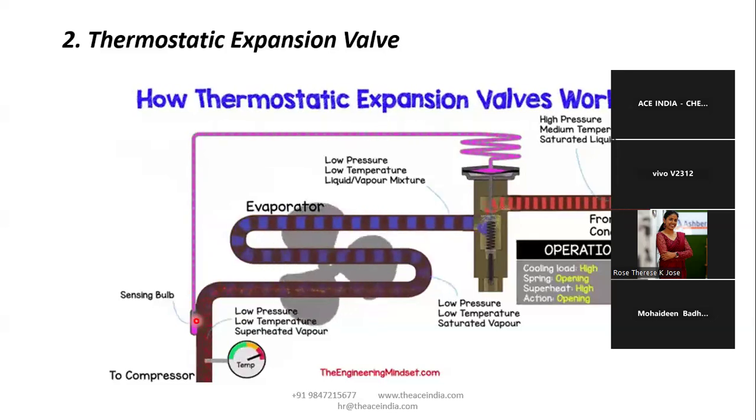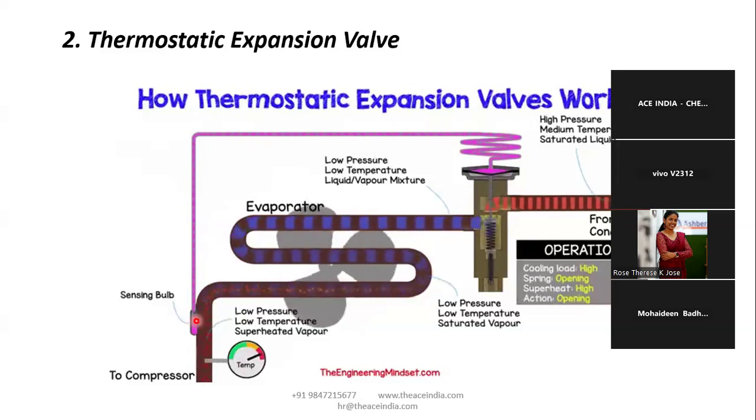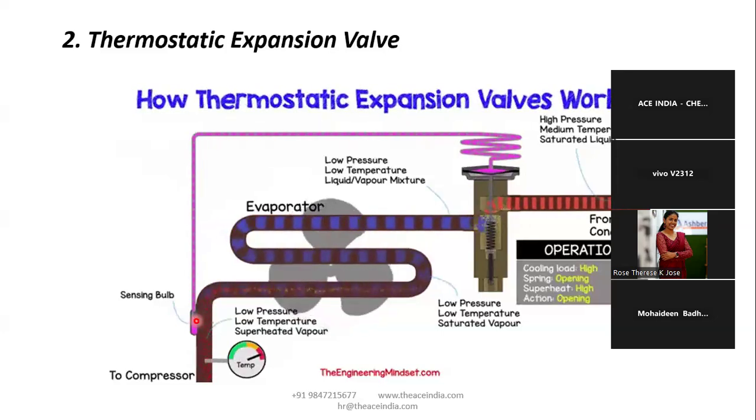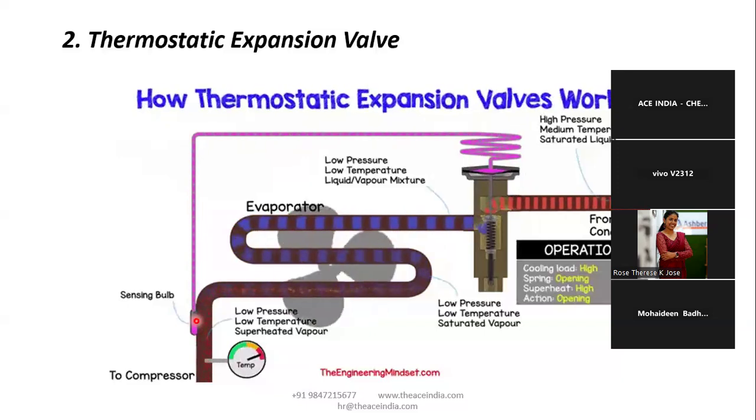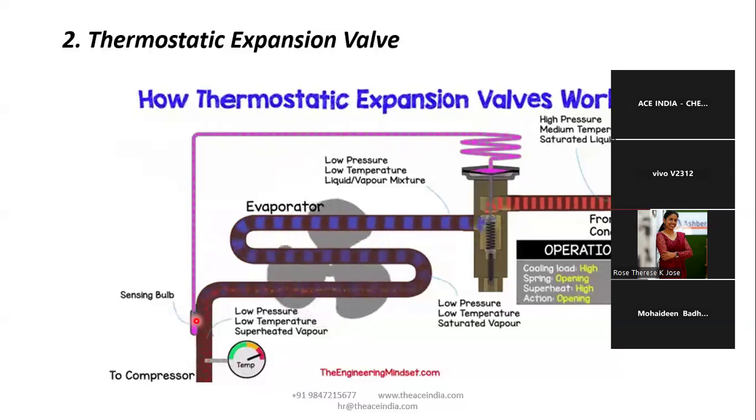And normally these electronic expansion valves are used preferably for systems called VRF or VRV, and technically you can implement them for chillers also. So this is the idea of the electronic expansion valve. The other one pushes, the same thing itself; here, instead of pushing, it's directly opening and closing. So that's why I told you, you don't have to wait until the substance vaporizes. Instead, it's a direct opening according to the temperature rating that you've preset on the expansion valve itself. Okay, is it clear?